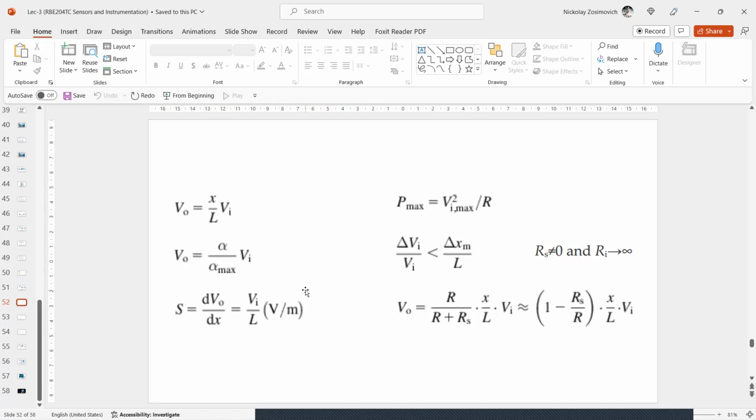The sensitivity can be increased by increasing the source voltage. Obviously, the maximally permissible power should be kept in mind. And when ambient temperature increases, the maximum allowable dissipation drops. It is wise to carefully check the data sheet on this aspect.